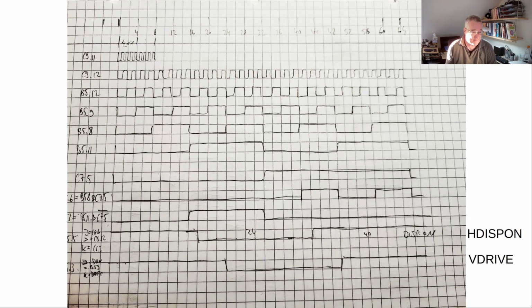This goes low when this value here is high, and then we have a falling edge on the clock here, and it goes up. I guess it's the same when the second one here is the other one. This is the J input, and the clock goes down here. And then we have a delay, just a delay, which is interesting for the vertical drive. So the vertical drive actually reaches into the displayed area. Well, strange, but works.